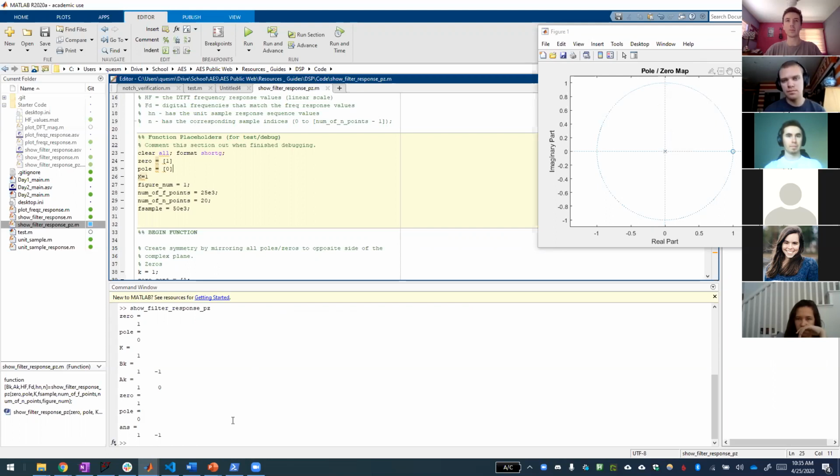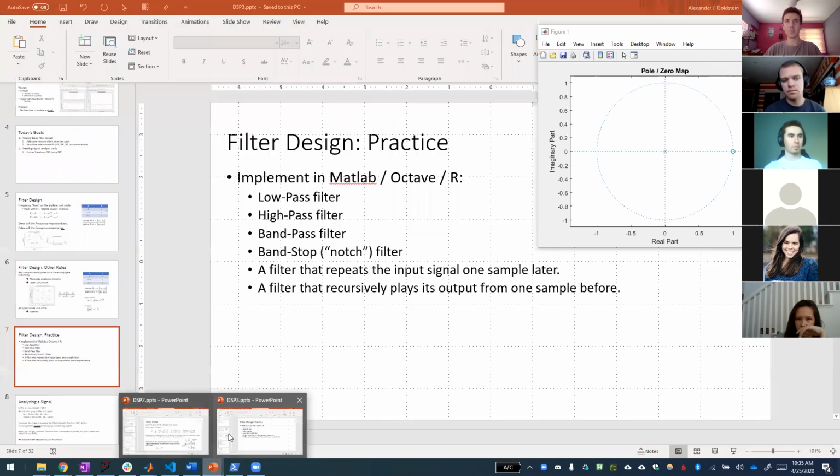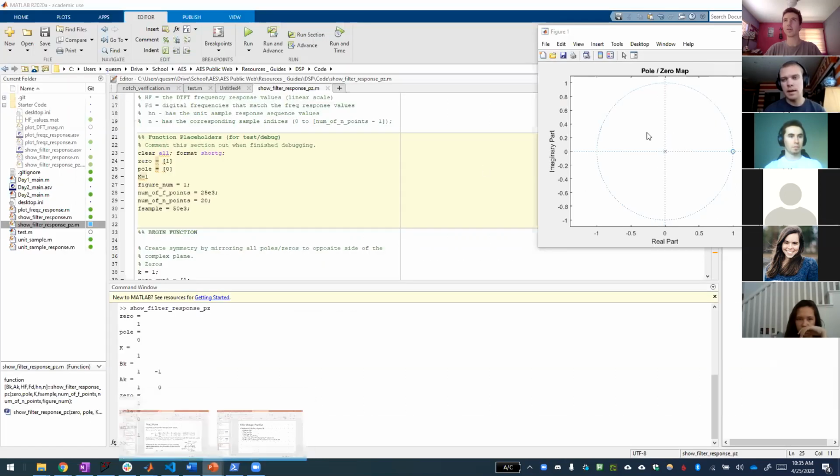And did we say we were making band pass or band stop? Band pass? Okay. So yeah, we want it to look like this then. If you place the pole nearby that point, it should shoot up there. And as long as you put zeros on either side of it, it'll pull down. So you can move these zeros closer to get a sharper transition.